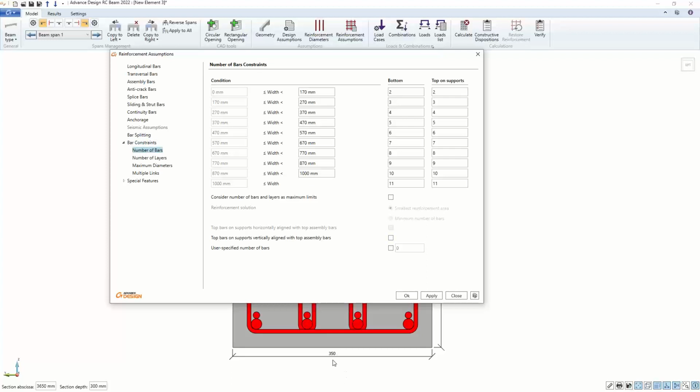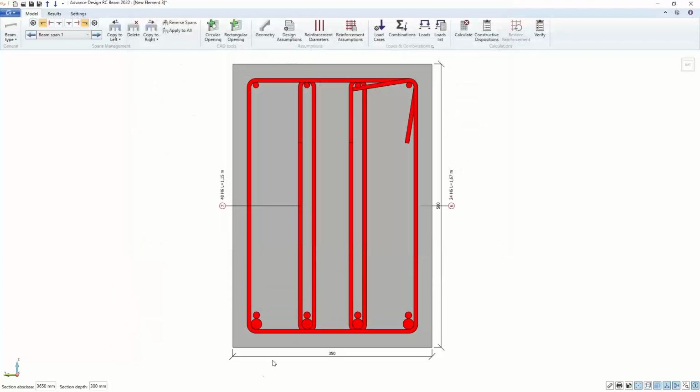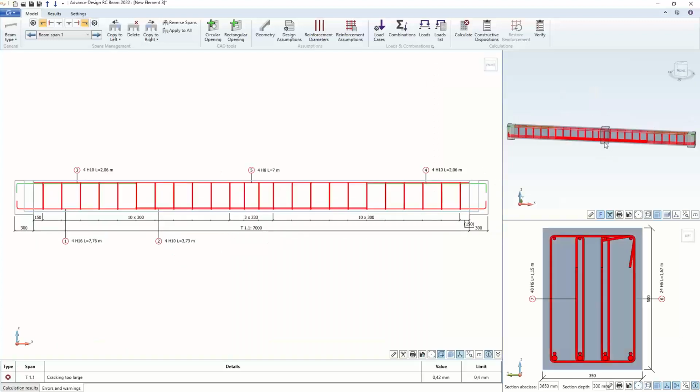So by default, for the width between 270 and 370 millimeters, 4 bars are generated, 4 columns of bars. What is the diameter? I don't know, 16. And on the second level there are 10. It's on some sections, of course, on the selected section. But anyway,